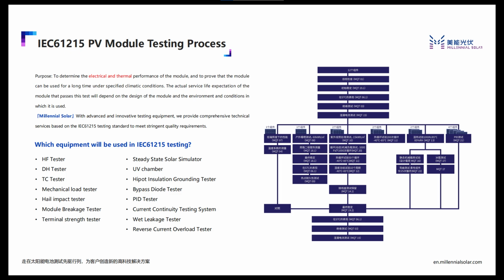Among these 5 test categories, some of the tests belong to the test requirements of IEC 61215, some of them are from IEC 61730, and some of them are from the requirements of incoming material inspection before production. And in the end, when the module is delivered to the installation site and in the operation stage, we will also need tools to run checks on the panels, which we call maintenance routine. So without further ado, let's go into the content.